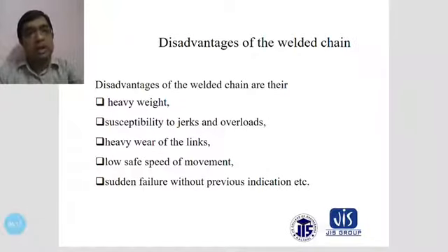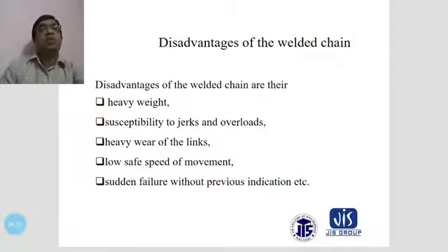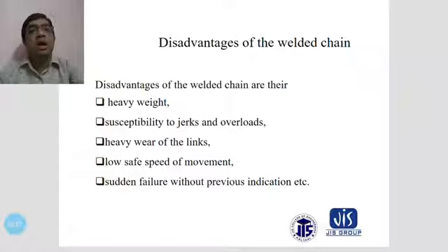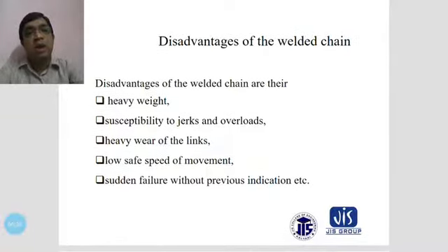Another thing is the susceptibility to jerks and overloads. Because of the heavy weight, jerking also has to be considered. During overload, since this chain carries the maximum load and is heavy, difficulties come. Another is heavy wear of the links. Since so many links are joined one by one during the manufacture of the welded chain,